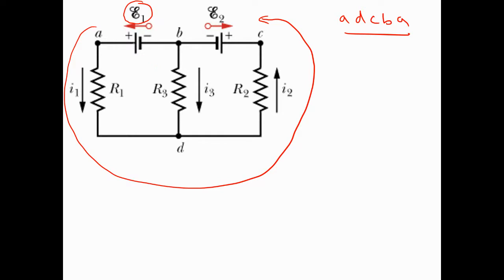Now you have to separate the battery. So my EMF of the battery is the strongest. Which one is the weakest? EMF2. Because my arrow is opposite to this arrow. Am I right? So what should be the sign? Minus. Negative. Clear? Which is exactly equal to the product of the current and its resistance. My dear, listen carefully. This is my arrow of the current, and my I1 is also in the same direction. So what should be the sign? Positive or negative? Plus. Very good.